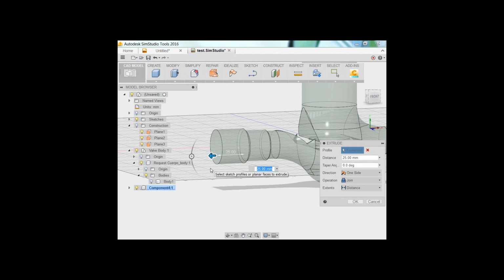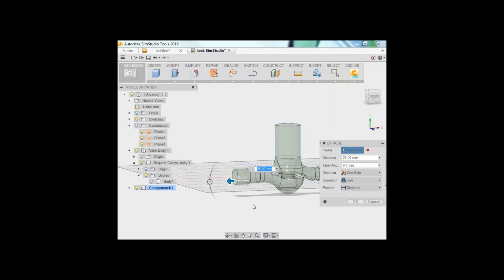And again, good on Todd for catching that, where the press pull actually brought up the offset faces, which continues trying to create in the same direction that it was making. So in this case, you just go in and manually click the extrude. That's all you had to do in that situation, and you create a longer end right there.